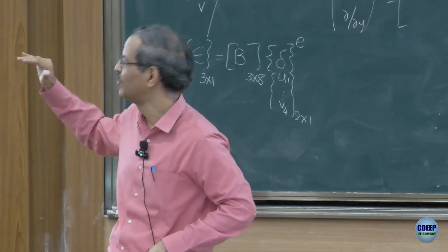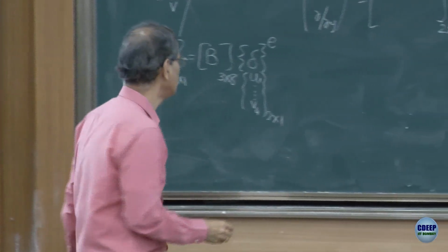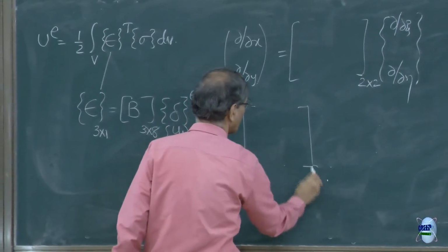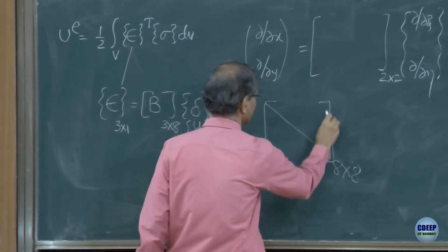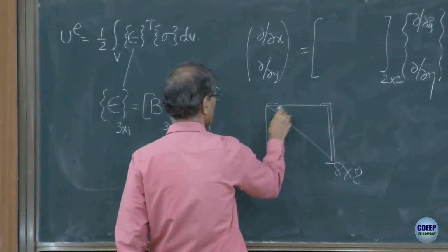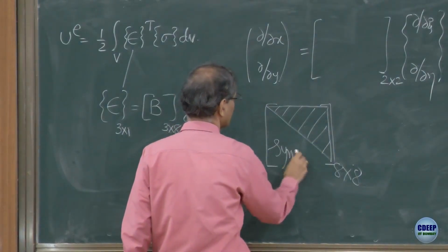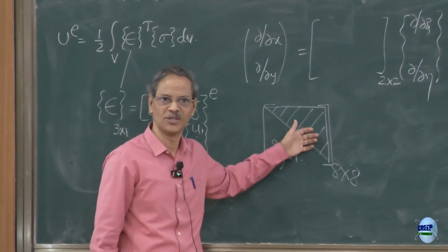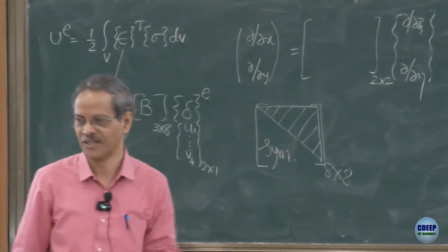So, you will still need to evaluate 36 integrals. That 36 comes from the 8 by 8 matrix. So, the leading diagonal and then this. This is symmetric. So, this is going to be 36 coefficients. So, these 36 double integrals you will need to evaluate.